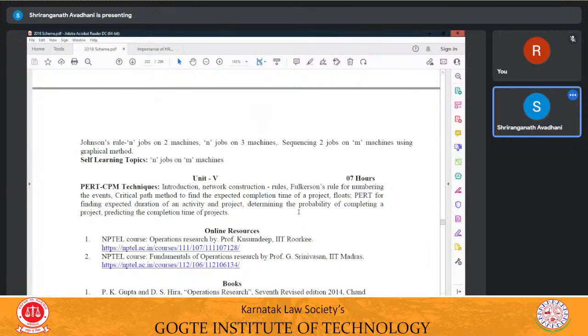So when you give priority to these activities and connect them, that path leads to a critical path. Then we'll be calculating different floats like total float, free float, and interference float. All these floats we calculate based on the earliest start time and total finish time.